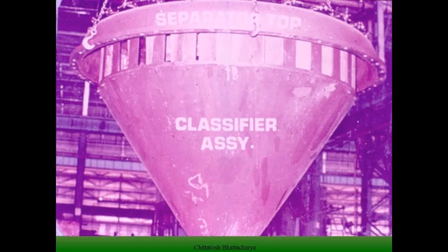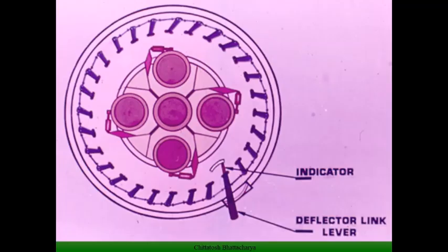And there is a continuous recirculation due to the presence of the classifier within the milling system. There is a 3 to 5 times recirculation within the milling system, so whatever coal is coming and whatever coal is moving out of the classifier, there is a continuous movement of 3 to 5 times across the classifier.